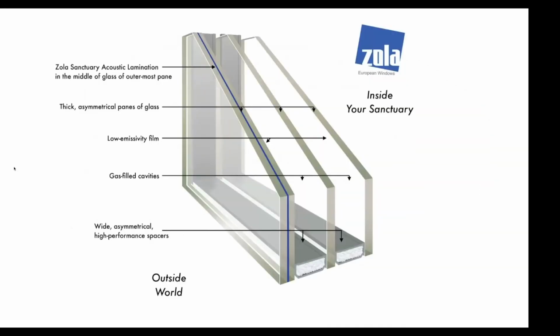How do we do this? What are the components of glass to handle the sound and the shutting down of it? The main component is that the outside piece of glass is a laminated piece of glass that has an interior plastic meant to shut down sound and not transfer it.